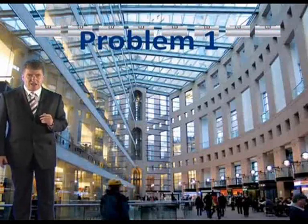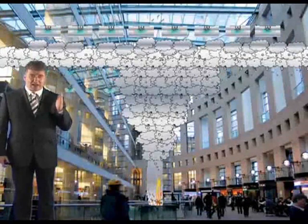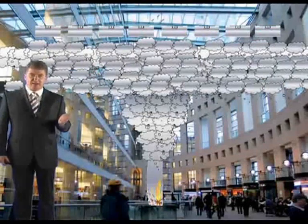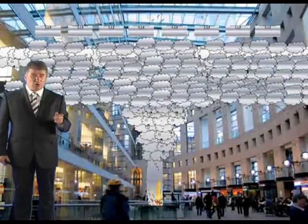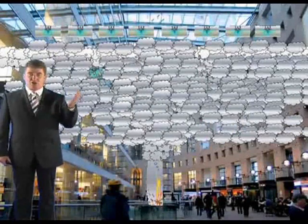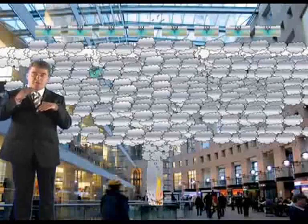Now, there are a number of problems which must be considered when putting sprinklers in the atrium itself. The first problem is that a natural ventilation system relies on the buoyancy of the hot gases. If the cooling of the smoke by the sprinklers is underestimated, then the smoke may lose all its buoyancy and the system will fail, especially if it's close to the operating temperature.